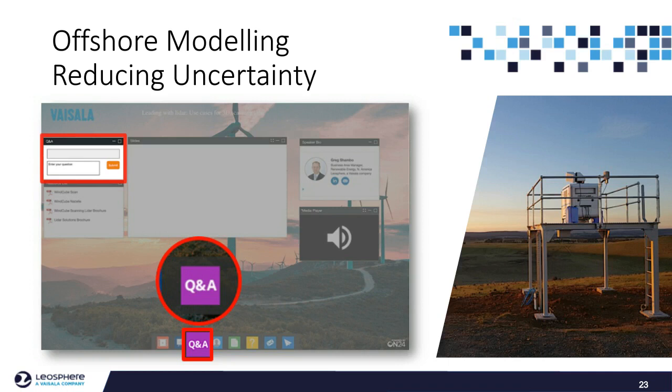Yeah, that's a kind of complex question. Well, the system can be validated. For example, we do the validation at the factory by comparing the scanning LiDAR with a golden LiDAR, but the certification will have to be done following IEC requirements from the standards. The only thing is that the scanning LiDAR does not have an IEC standard to follow, so the certifiers follow their best practice criteria. Okay. All right, let's move on to the next one.